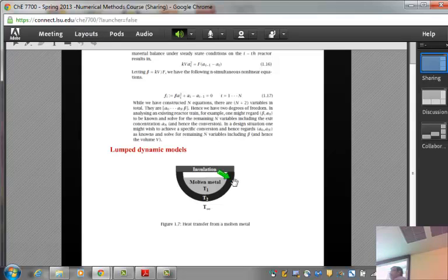You would expect them to be very similar. But if I take the temperature close to the inner one, close to the outer one, would you expect them to be the same? That kind of an intuition you need so that you can develop the model correctly, because the temperature gradient is going radially out, for example. Okay? And because the crucible may not have a very good thermal conductivity, it may not be a good assumption to say that it is homogeneous, it is lumped. But we are going to make that assumption in this case, keeping in mind that that may be the weakest point in your model. Okay? Any questions?